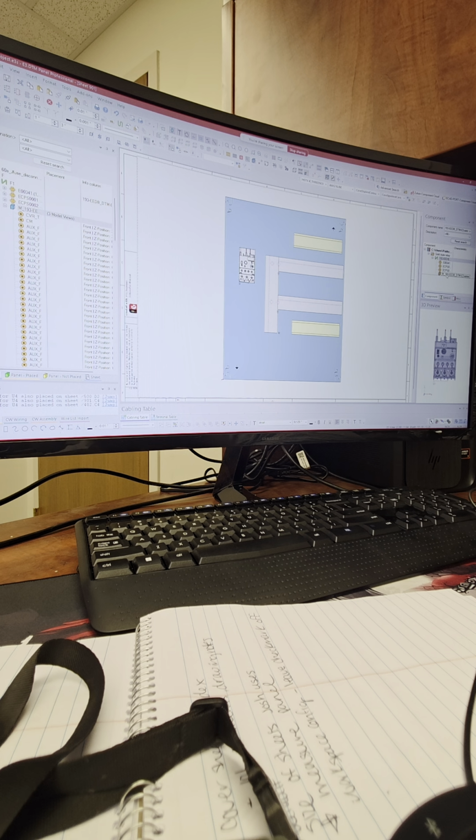Right. But if you are designing this, obviously you know what you're committing, you know why you're editing it, then you would just come here to this component, either from the model perspective, like putting your mouse on it, or if you select it on a device level, one level up, or even from a folder or library level, you have the option to right click and say update in project, or update all components in project. So when you select update in project, not the attributes, but actually the whole component, one level up, update in project.